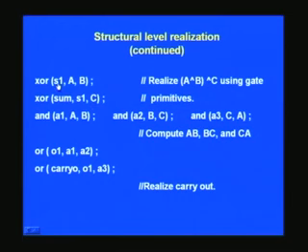So here what you see is the intermediate signal, and this invokes a primitive which is available in the libraries of Verilog. This is exclusive OR which you are already familiar with, and similarly this is AND and OR, and the first one stands for the output of that gate, whereas the rest will be the inputs.